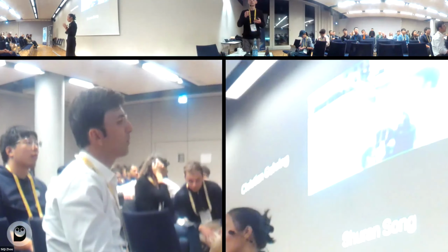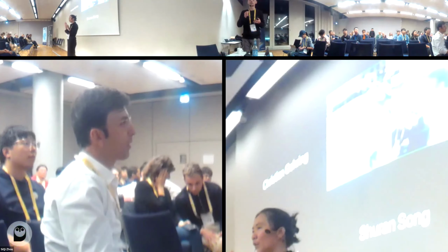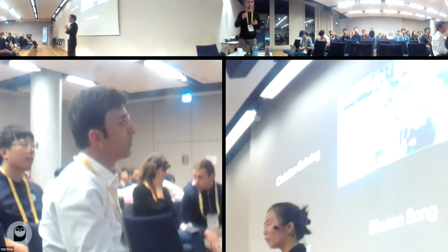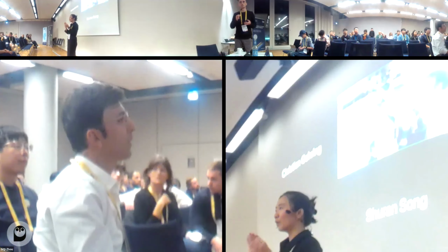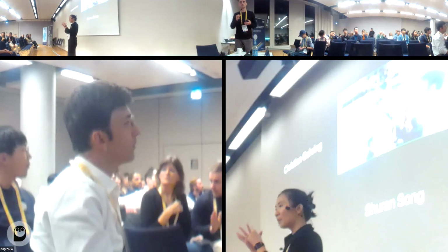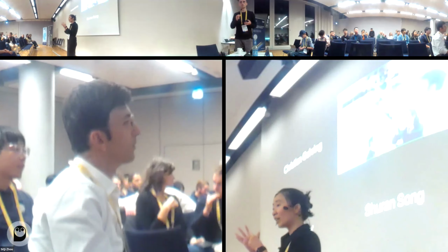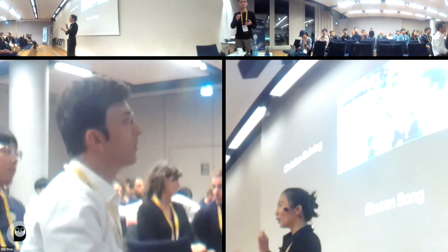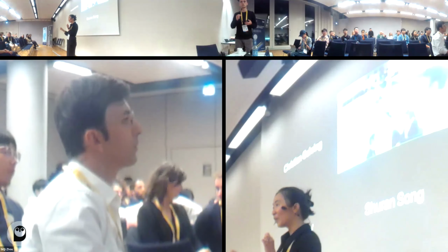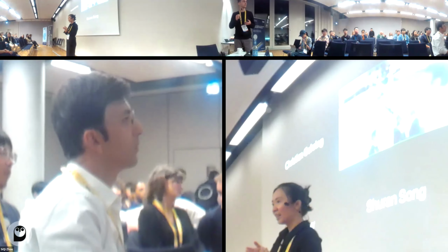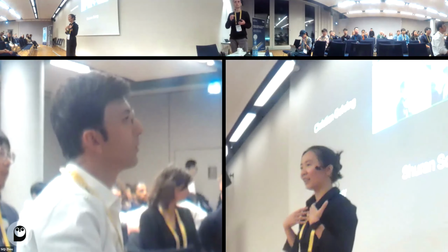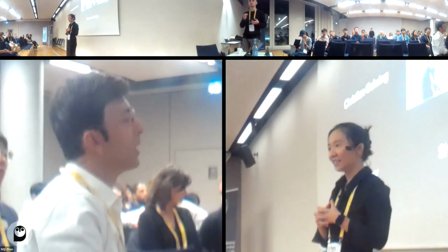So I think before, the reason why people didn't use a microphone as a tactile sensor is because it's very hard to get explicit contact information, right? If your policy requires contact position or contact force as an input, then it's very hard to explicitly decode that information and put it into the policy. But if you learn it using behavioral cloning, you don't really care about explicit state information. You just need the raw input. That makes it easier to use microphone data.